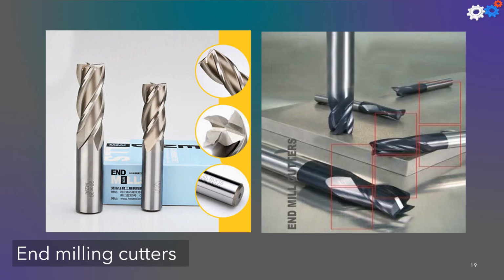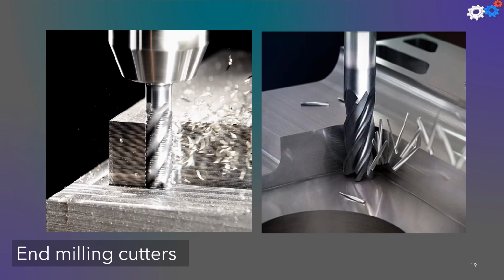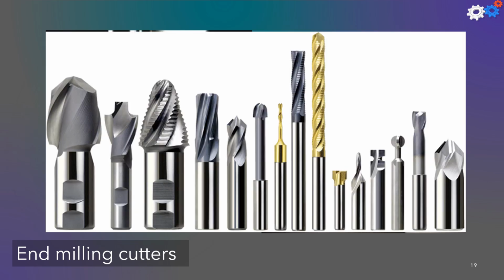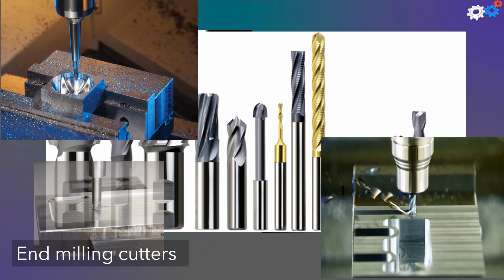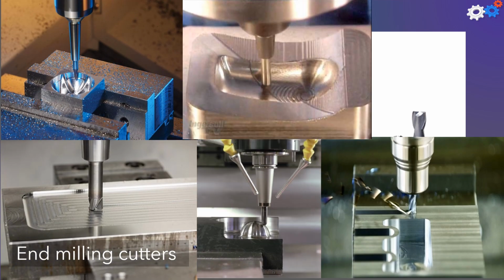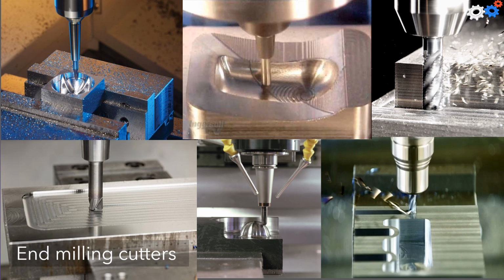An end milling cutter looks like a drill bit, but a close inspection indicates that it's designed for primary cutting with its peripheral teeth rather than its ends. The end mill is designed with square ends, ends with a radius, and ball ends. The end mills can be used for face milling, profile milling, and pocketing, also for cutting slots, engraving, face contouring, and die sinking.